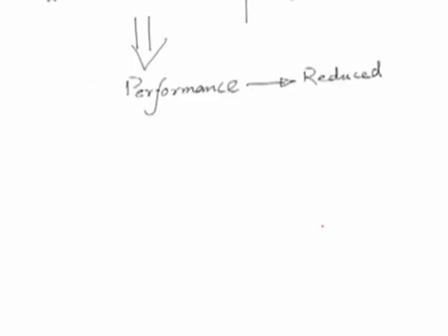Therefore, the process is advantageous. Furthermore, the vibrated workpiece may help in stirring the abrasive slurry during machining to increase the efficiency of the abrasive particles around the machining zone and remove debris. This is another advantage as far as applying vibration to the workpiece is concerned.